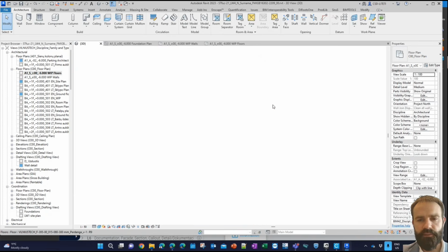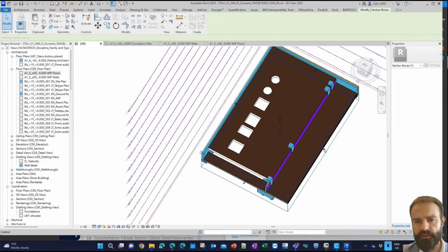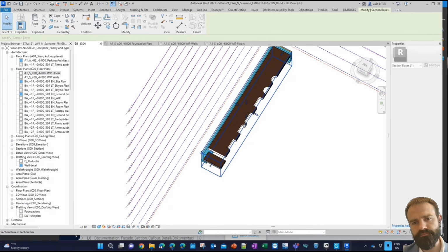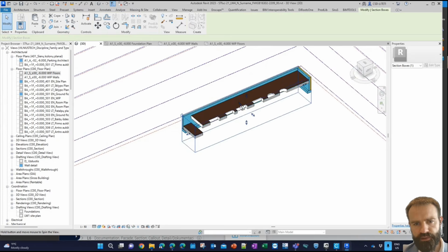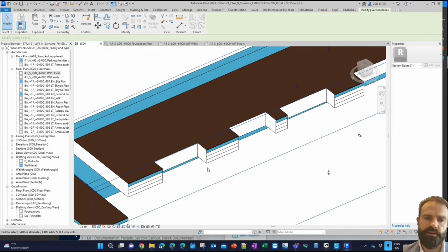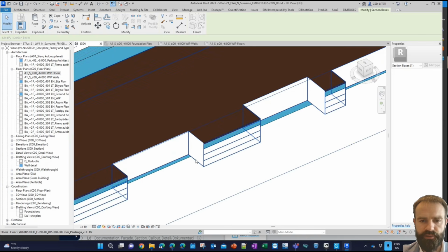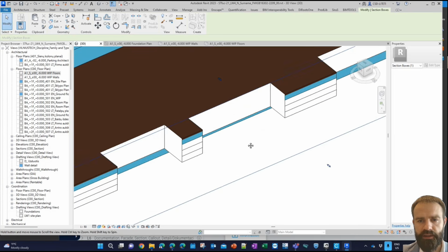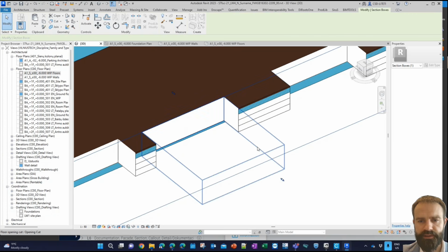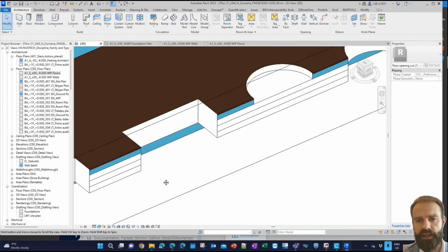And if I go to the 3D model and select make section in this position. So the typical Revit tools to create openings make a section through all the elements. And I have these blocks which are representing the opening.